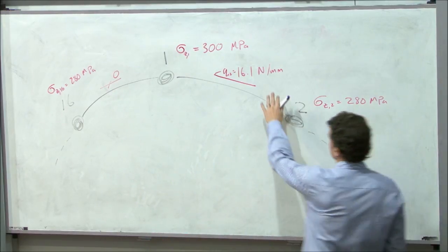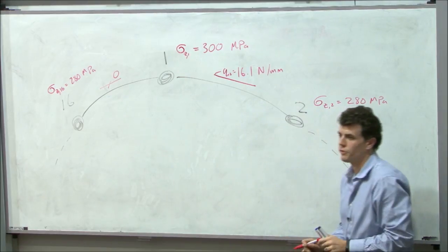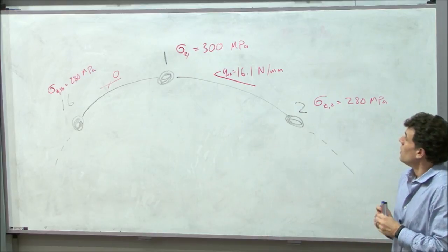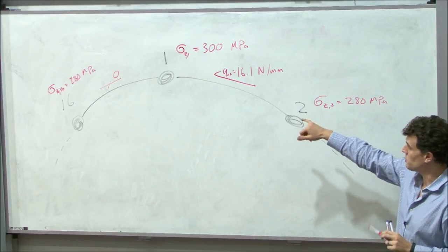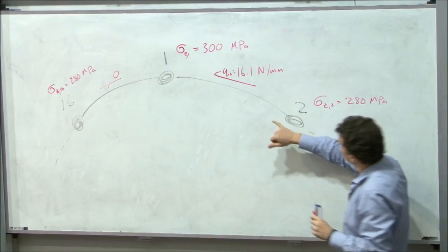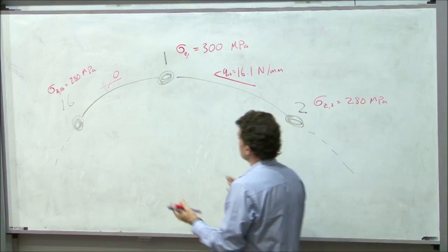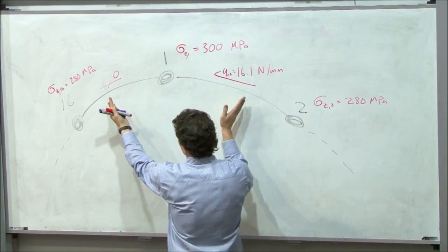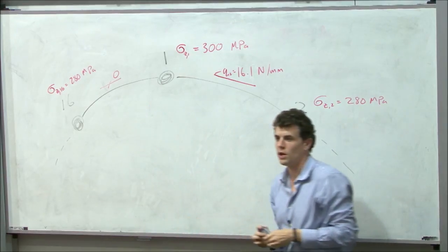Now, obviously each panel that you go to, these numbers are going to be different. So what does this tell us about stresses? Well, remember this is just an idealisation. When we made these booms, we were actually taking material from around here and plonking it into an idealised area.